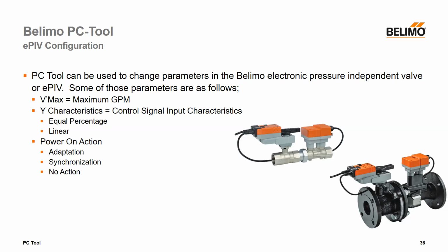But again, as we're just moving water from high pressure to low pressure or from supply to return, we're not engaging in any heat transfer. So we don't care if the water stays on the supply side longer. In fact, we don't want it to stay there. We want it to move as the differential pressure transmitter tells the controller to move that valve open to move water from supply to return, or again, from high pressure to low pressure.